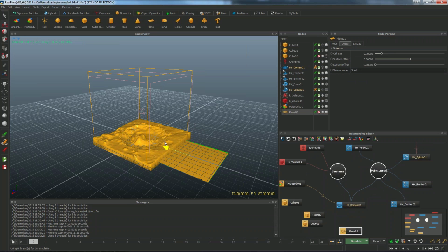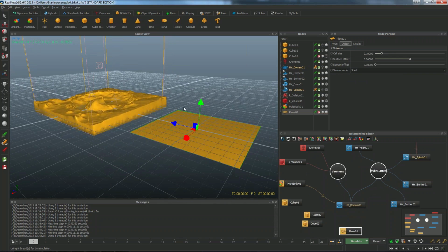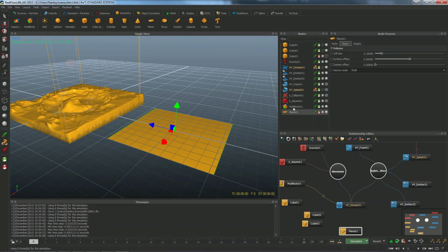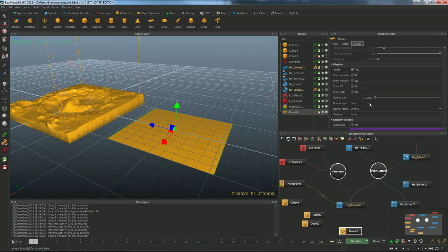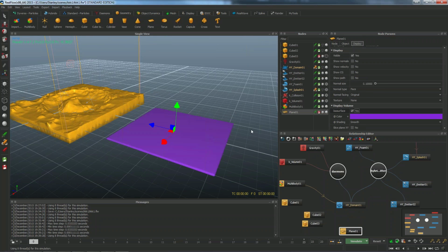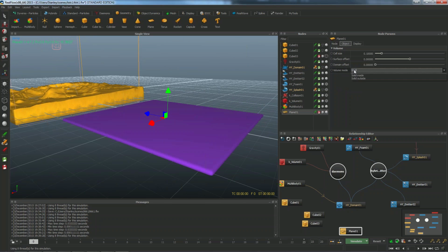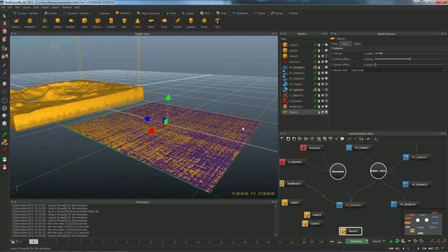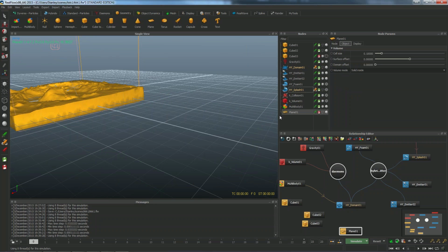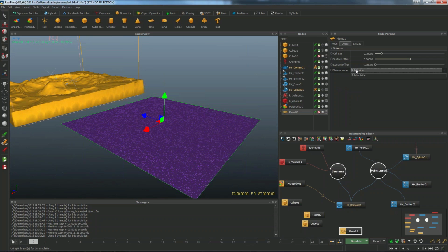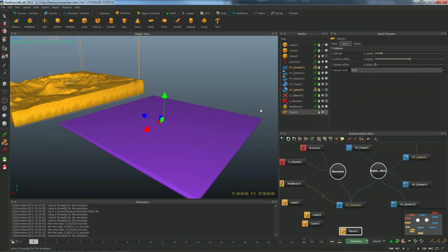I'm going to create a plane, and you don't have three dimensions here. So you have shell. If I display the surface, you have here the surface. If I display solid inside, okay, the plane is not... Sorry, here. You see strange things with the plane. So the correct thing for this kind of objects is to work with shell mode. Okay.